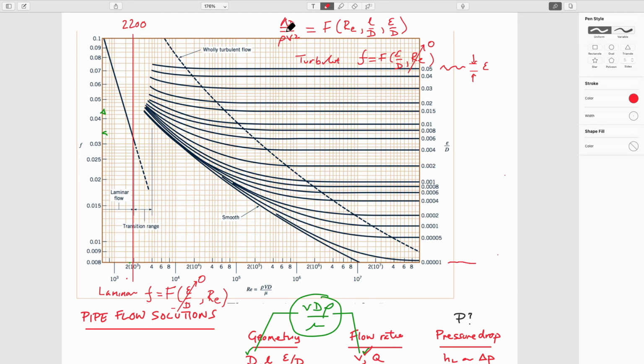This non-dimensional parameter here is equivalent really to what we're calling head loss. Pressure upstream, pressure downstream. If there's frictional loss in the pipe, then the downstream pressure is lower because it's working against friction. That's the head loss. It's the height of water from the upstream tank to the downstream tank, physically what it is. And the length over which it travels and the diameter of the pipe in which it travels is the length to diameter ratio.